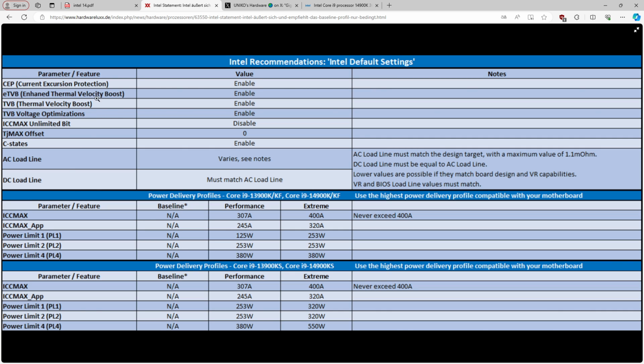Asus, I think, runs some kind of mix of these. Anyway, this is the main reason why Gigabyte motherboards have insanely high low load voltages, even compared to Asus boards. Even though neither of them have any power limits, it's pretty typical for my Z790 Aorus Extreme X, after a clear CMOS at low loads, for the core voltage to easily go above 1.5 volts.